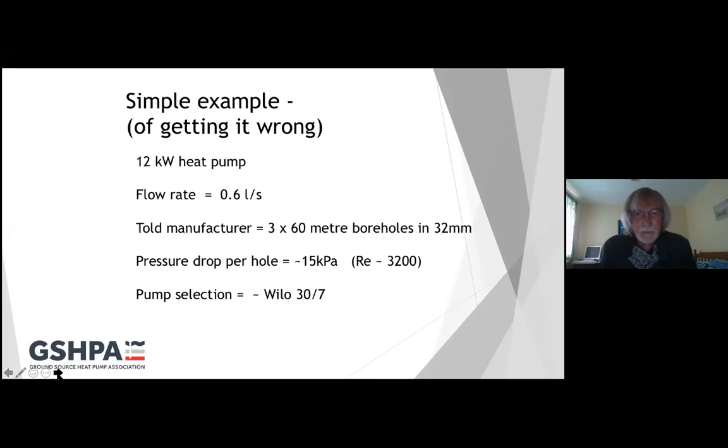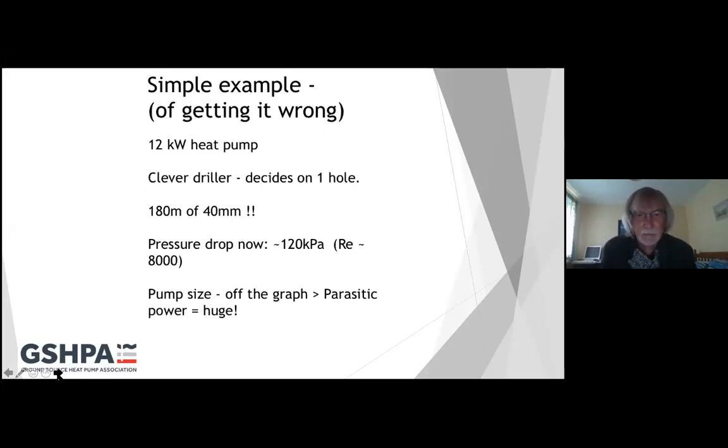This was a by-the-by that happened to me. I was asked for a quick and dirty sizing on a heat pump while I was in a car somewhere. 12 kilowatt heat pump. I kicked back and said, do 3 60 meter holes in 32 mil. The pressure drop would have been about 15 kPa, and it would have been a little Wilo 37 circulating pump.